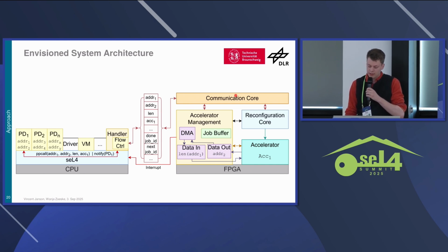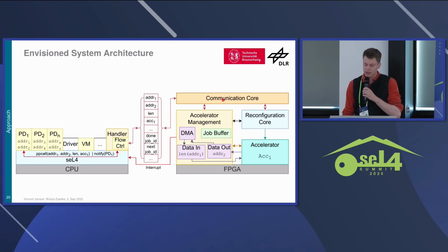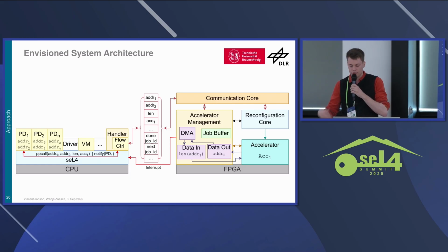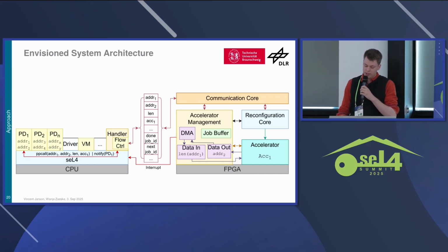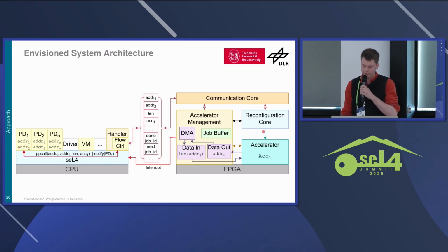Via the AXI Lite, we can then receive this information, or basically read the change of the configuration registers, and in turn have the accelerator management, which internally has a state machine for the job scheduling of individual jobs, take care of a job. Mostly what this means is, if the current configuration is fine, we don't need to reconfigure. If there's a problem with the current configuration, if we need a different accelerator core than the ones which are currently loaded, then we can reconfigure.